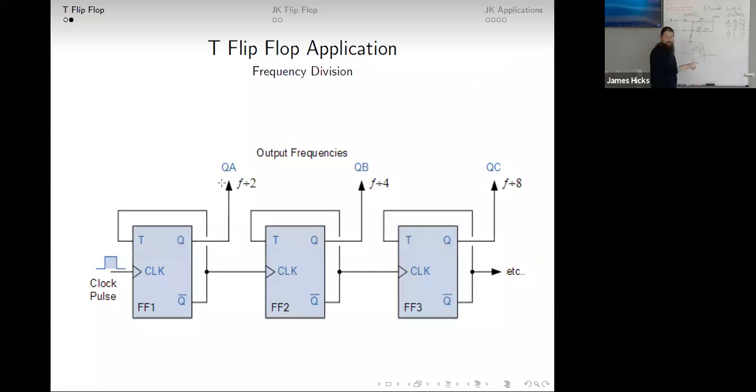But it's just multiple toggle gates that are inserted. So what's going on is our first flip-flop, first toggle right here, that's the one that's getting a repeating clock pulse. So that clock signal going in is just an infinite string of square pulses, on, off, on, off.